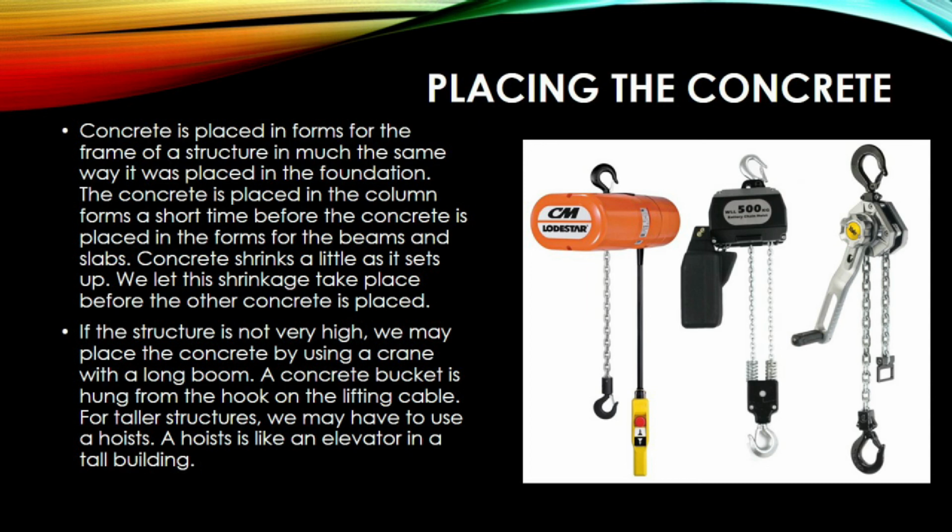If the structure is not very high, we may place the concrete by using a crane with a long boom. A concrete bucket is hung from the hook on the lifting cable. For taller structures, we may have to use a hoist. A hoist is like an elevator in a tall building.